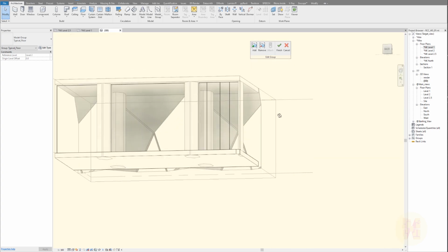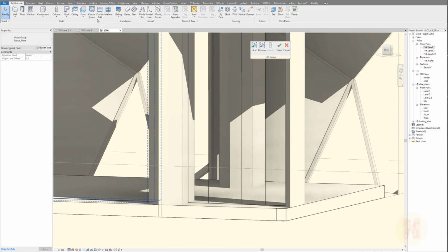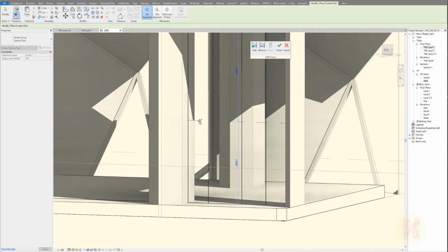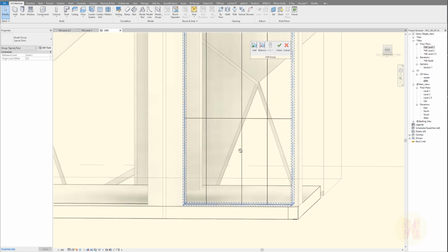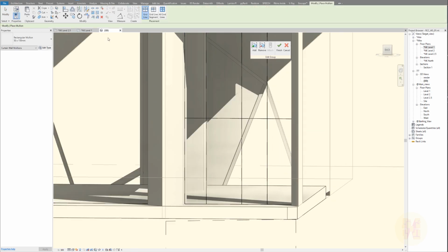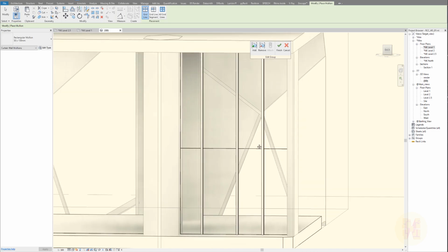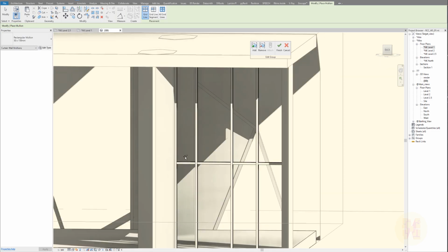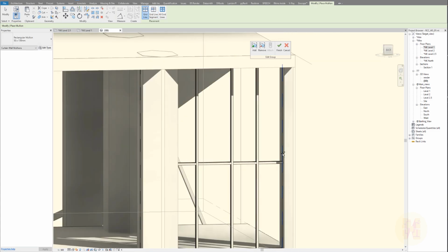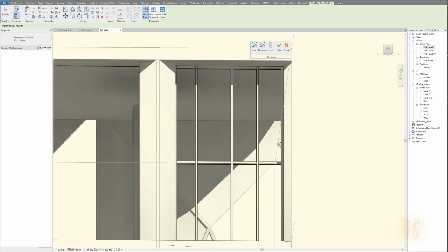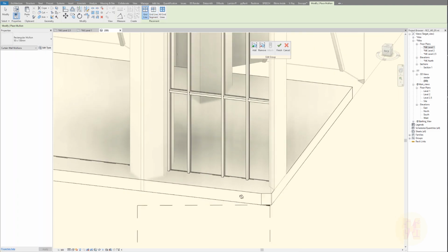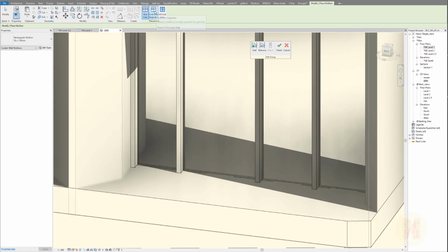As you can see now, we can see what's going on in 3D, and we also need a grid for the height. I recommend using not less than 2,100 millimeters. 2100. And now we can use the mullions. Let me select the mullions, and we can place them one by one. So it will be something like this, and of course don't forget the right side and left side connection, and the highest one. Here I will not use the full line, I will use only the 4 segments.